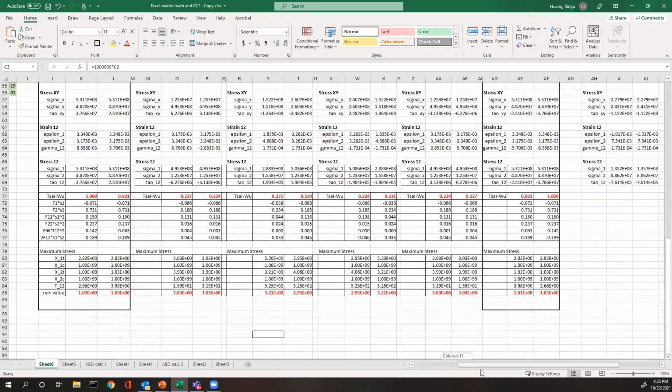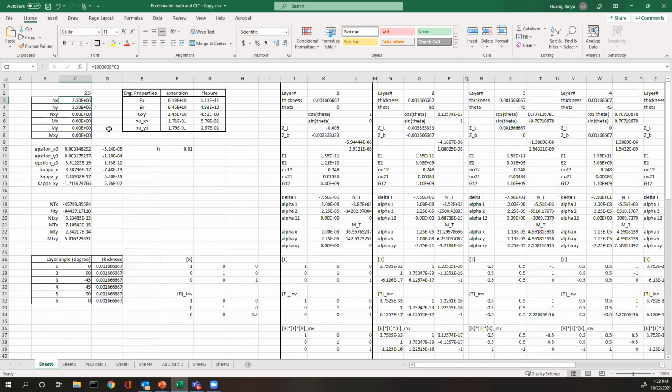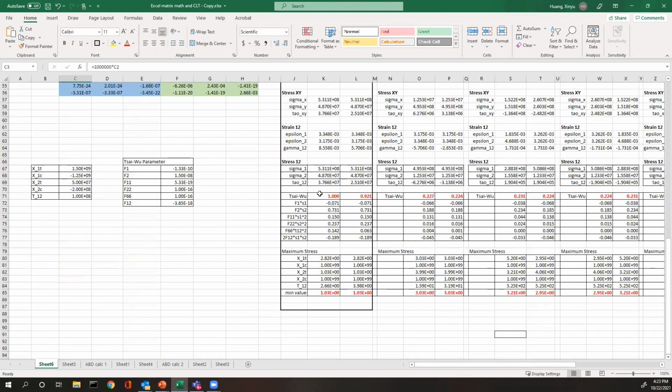So basically what I did, I simulated, I load this tension in the XY direction proportionally. At this low threshold, I have a failure here. This is the failure here, okay. And I want to determine what kind of failure mode it is. Let me look at this number. So this is actually 2-direction tensile failure. See, the 2-direction is hitting this, is the lowest number.